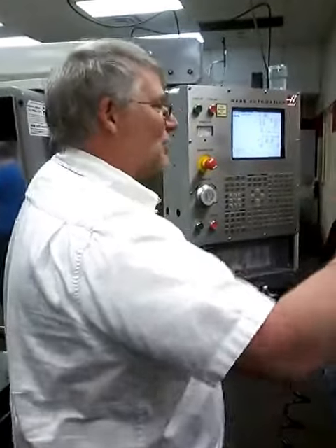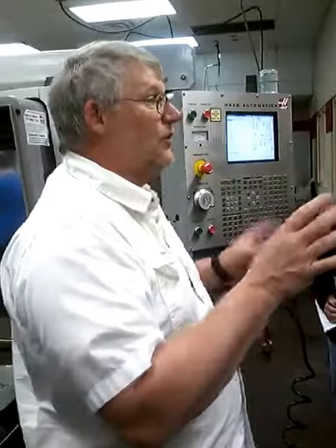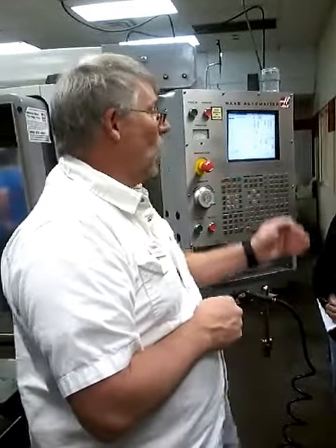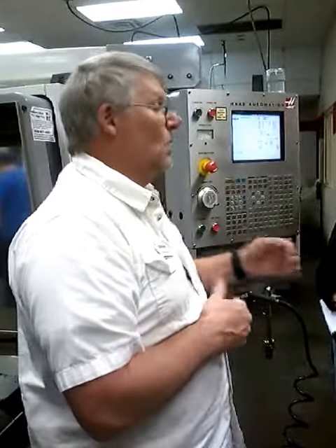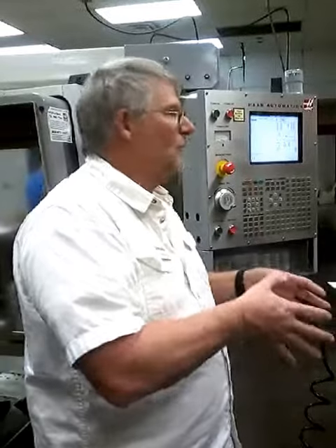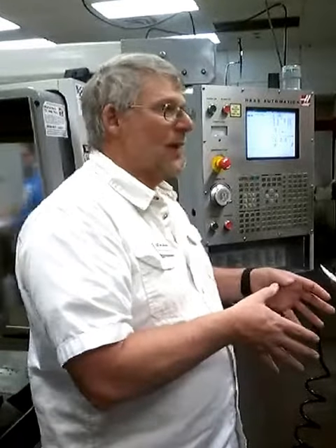Talked about in the classroom what a fixture offset was. It's the distance from machine home to where we want our part program 0 to be. We're basically telling the machine where our part is and where we want our program to run. Everybody cool with that? I'm going to use an edge finder to do it today.